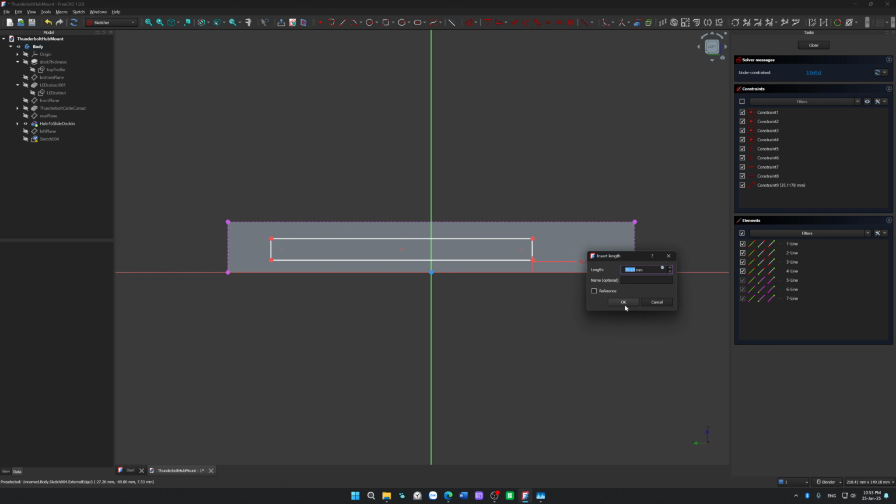But this is from the rear, so we have to accommodate for the thickness of the material also. So it would be not just 30, but have to be 33 millimeter. Boom. And from this side, the left side doesn't have to accommodate for the material thickness at all, so we can be a bit more generous.